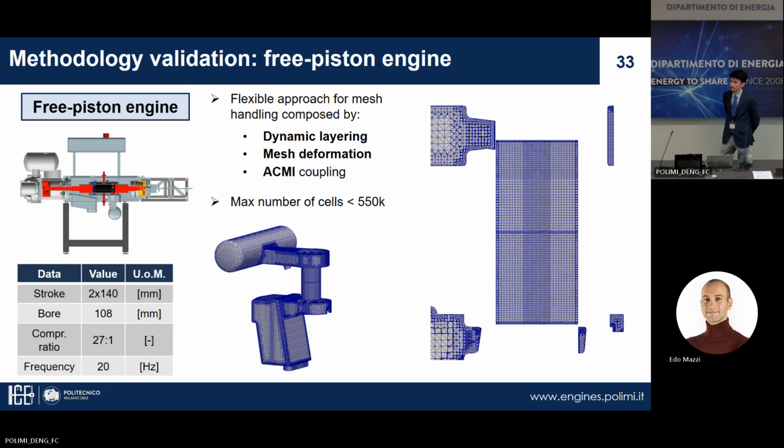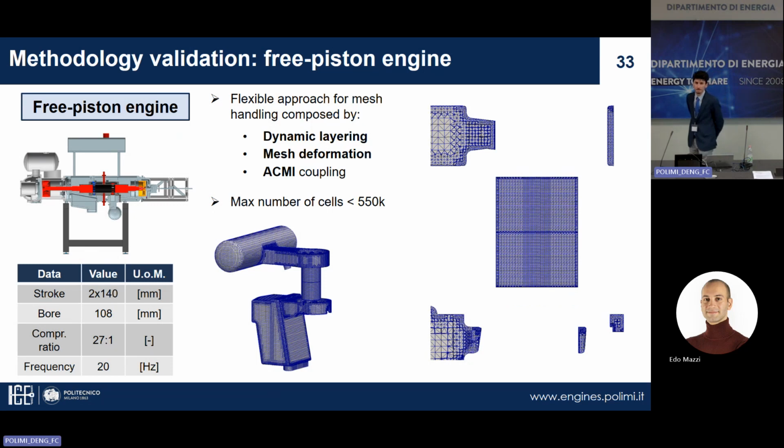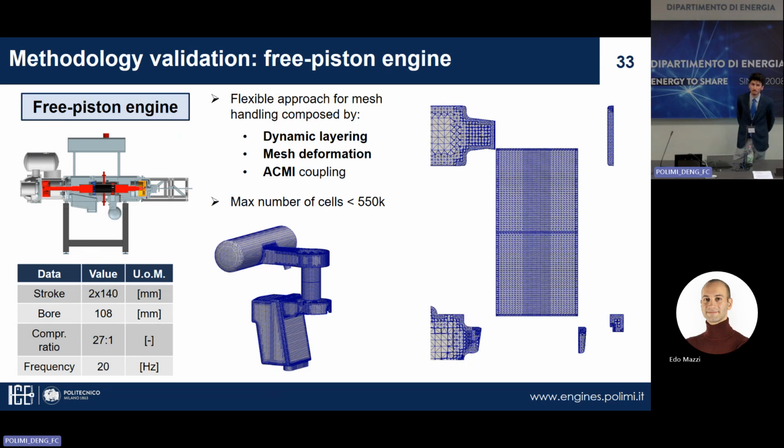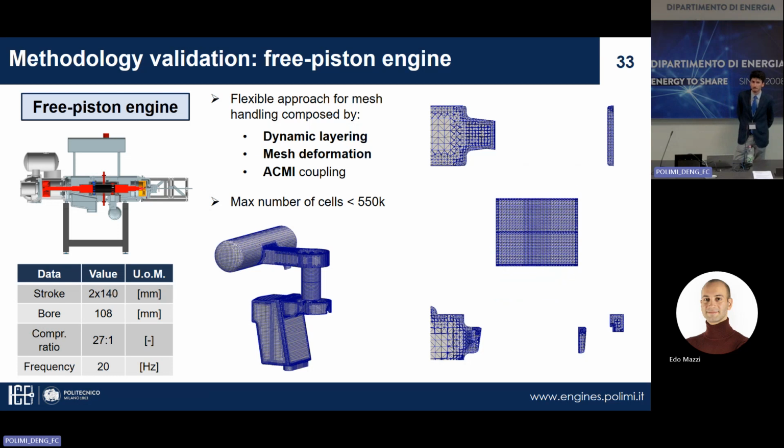Another question? Just a question that could be referred to a lot of the users that are doing simulations in this environment. I'm curious about when you have a variation of the geometry and also in the mesh, and every time you have a different mesh, are you able to give to the surface movement a velocity boundary condition which is derived from the kinematics of the system?